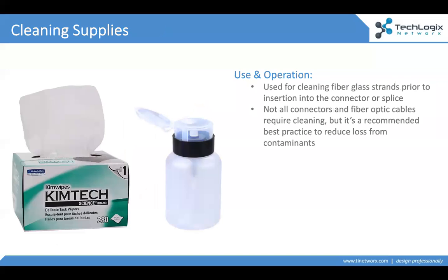And then the final part of this whole conversation, before we move into actually walking through the termination process, is cleaning supplies. Not all fiber connectors require you to clean them, but a lot do. And this is another thing. If you're working with a lot of fiber, it's important to have some alcohol wipes and an alcohol bottle on site, because that's going to allow you to prep the fiber depending on what you're encountering in the field. But just as importantly, it's very important that you keep your connections clean, the ends of those cables clean, the ports on your network switches or your video extenders.